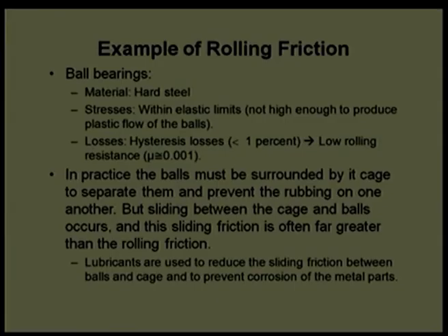However, we know rolling element bearings come with cages, or separators. We provide a cage to separate the two rolling elements. The reason is, if one rolling element is disturbing another, as in fully complement bearings, load carrying capacity will increase, but there will be chances of more friction due to rolling between two surfaces itself. They will start retarding each other's motion, and that will create a high coefficient of friction at the interface.